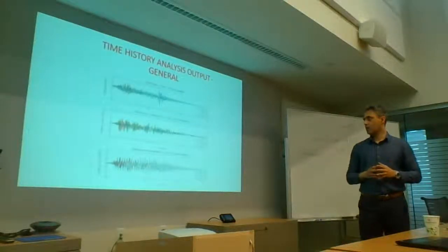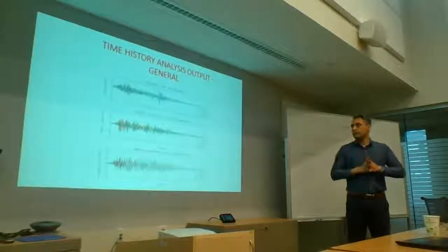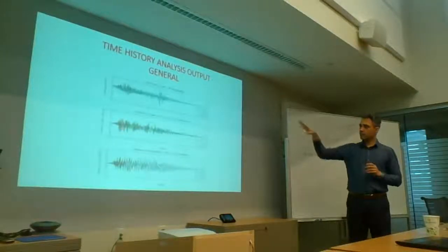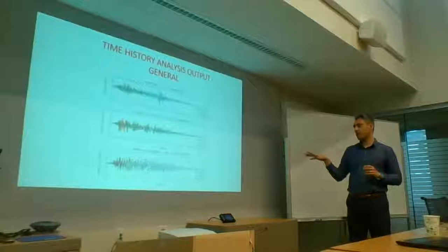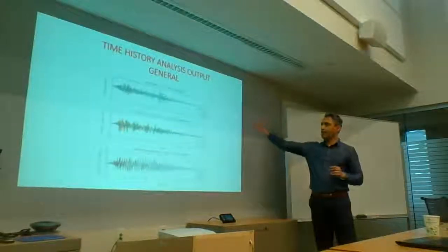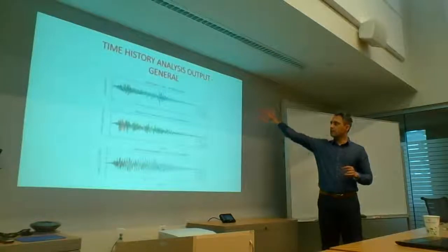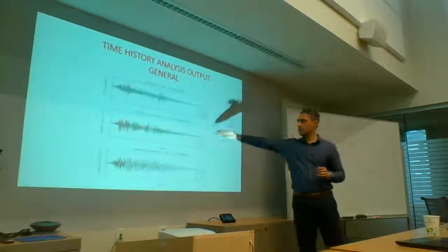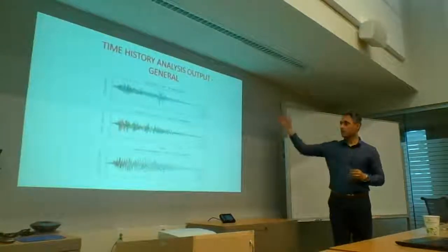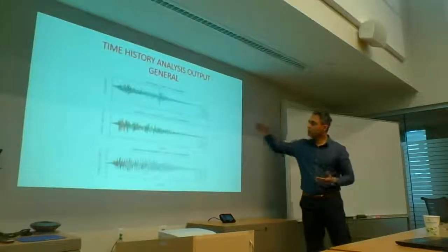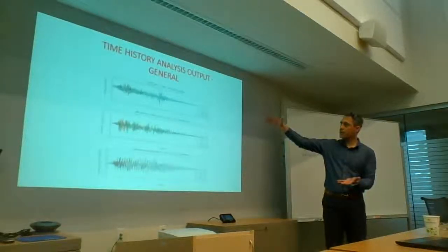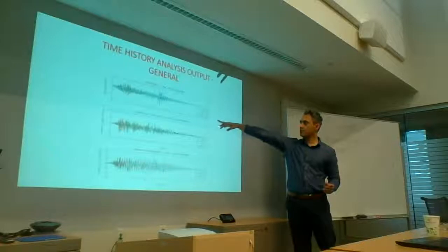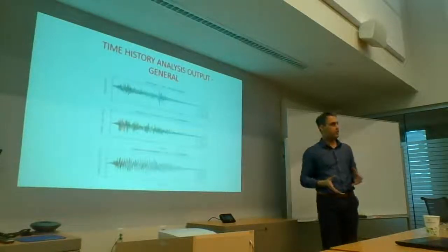Now, you've got all that stuff, what are you going to do with it? I think plotting is a great thing. So you run the analysis, and this is showing a time history response of an element, a column element. The axial load varies like that, the moment varies like that, and down here is the transverse moment, this is the longitudinal moment, and up at the top is the axial load. Then you can see what bounds you're dealing with. In this case, I'm dealing with about -1 meganewtons to about 6 or 6.5 meganewtons of axial load in my column.